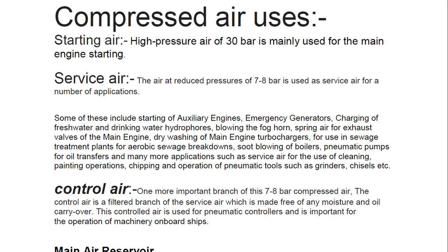Then we have service air. When we talk about service air, with the help of a reducer valve, this air which is at 30 bar is stored in the same air bottle, because both the starting air line for main engine and the service air and control air are fed from the same bottle. So how does it work? This amount of pressure is not required for service purposes. What is required is 7 to 8 bar.